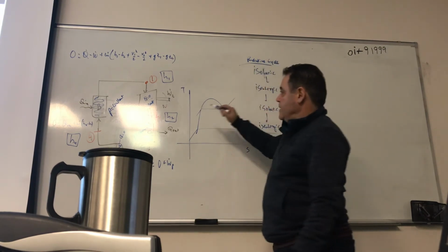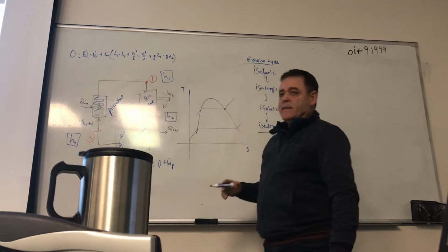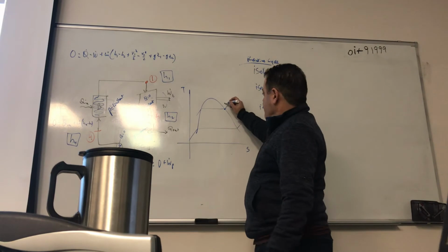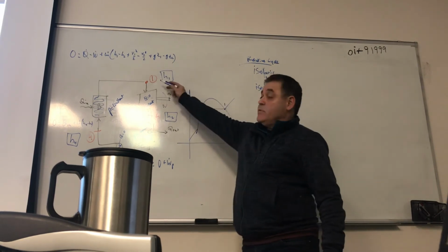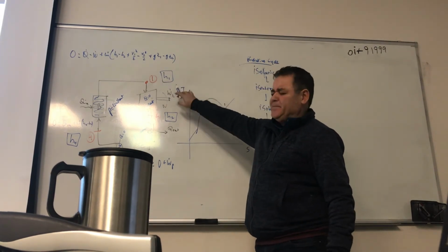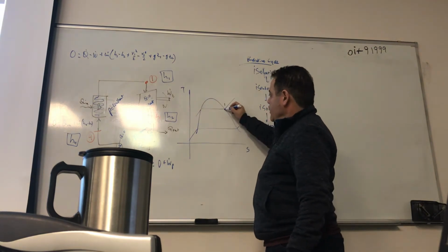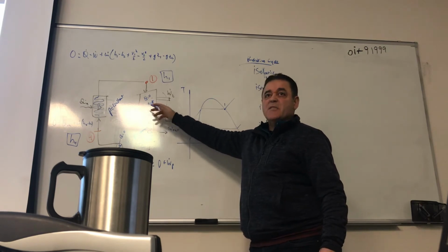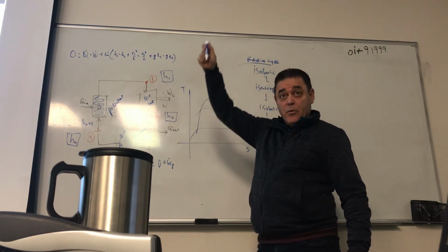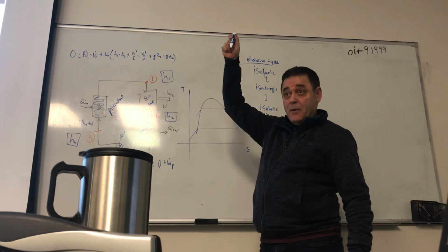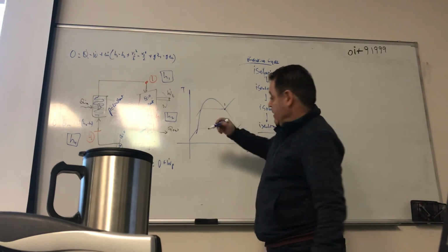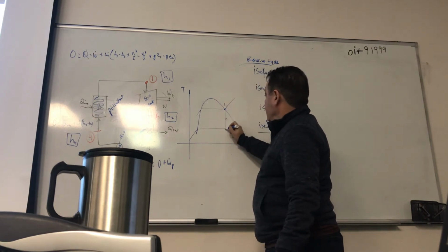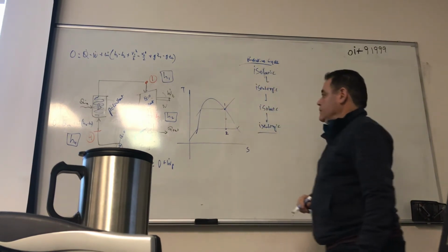Ideally, you would start here. At what state? All your liquid has become vapor, right? So state 1, remember, is always the entrance to the turbine. And you're coming down between 1 and 2 as in, what is isentropic? Isentropic with a lowering of pressure, that means I have to drop how? Vertically down, okay, because I'm on an S. You know, I come down like this. I end up at station number 2.